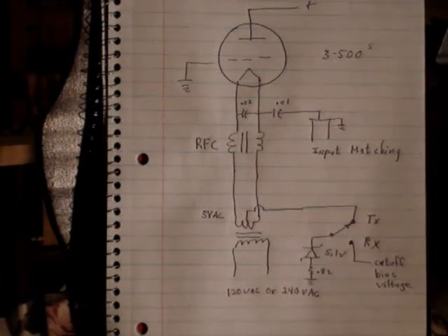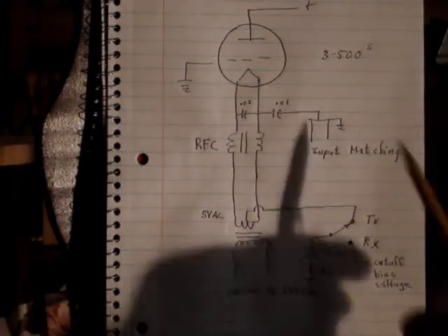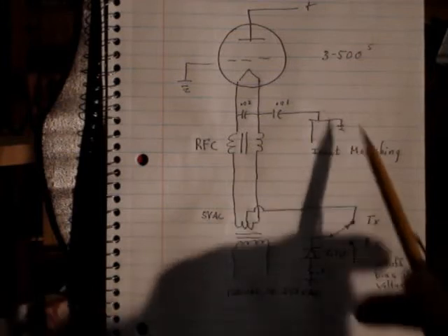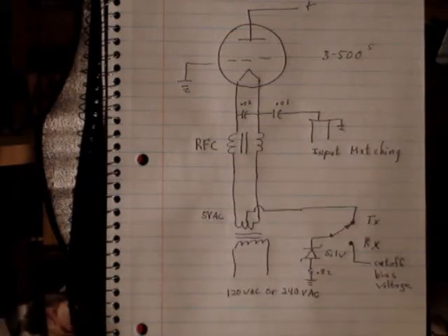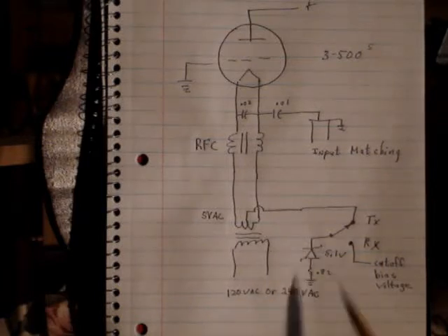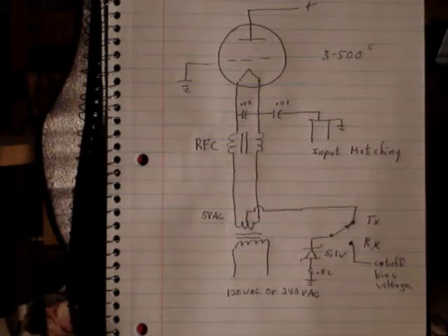So our whole discussion is going to be just to replace this one Zener diode here, and we'll show how we have to sense the input coming in, which in this case will be right here from the matching network, where we're going to pick off and sense when there's RF present. Then we're going to put a circuit in here to replace this 5-volt Zener so that the voltage will only be 5.1 volts when there's an input. When there's no input, it will go up to a higher voltage and reduce the current through the amplifier. So it really is not a very complicated problem, at least it doesn't look that way at first. So let's get into it.